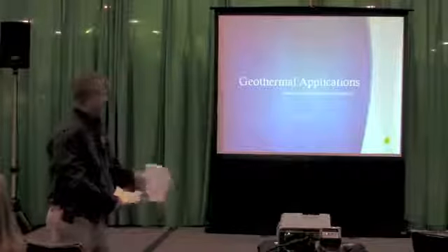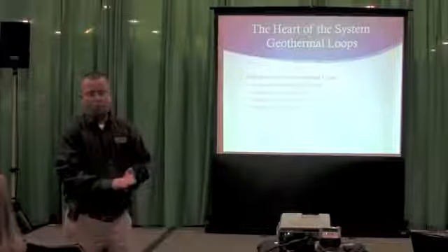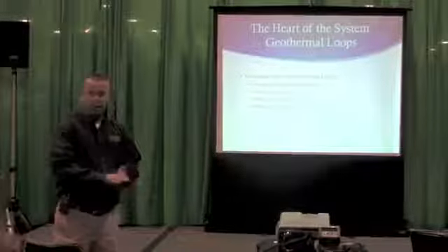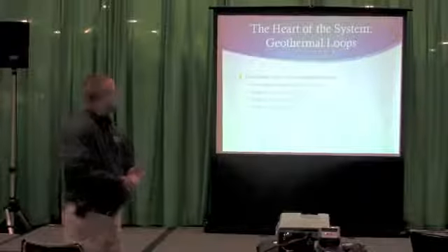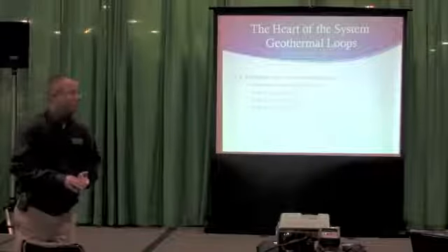Geothermal applications. There are 4 basic ways to use the water source geothermal systems. Our first is what we call the horizontal loop field. Our second is the vertical. And then we have a lake loop, and then we have an open loop.